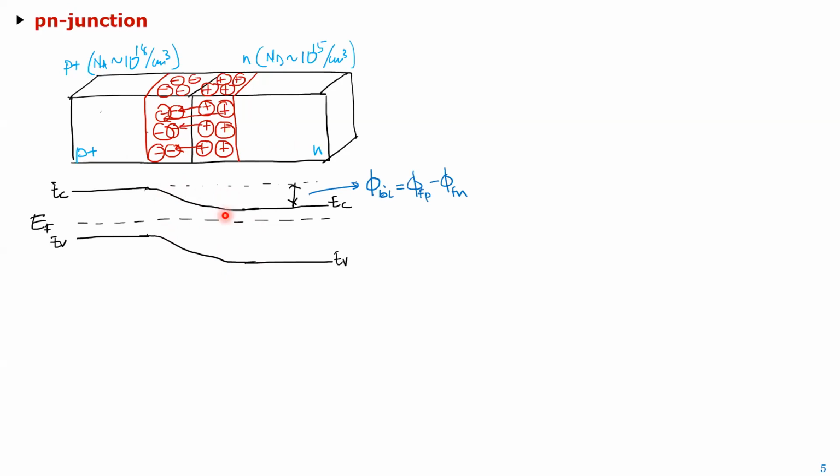And that's what I was saying, that where the band diagrams really help you is understanding when they come into contact. And the amount of this bending is basically the difference between the two Fermi potentials, or since one term is negative, it's really the magnitude of the two Fermi potentials. That's the built-in potential difference between these two p and n junction.